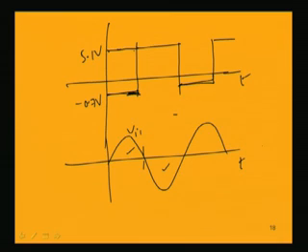In order to use it for digital circuits, we require a voltage not beyond around 5 volt for a 1 level or high level, and around 0 volt for the 0 level. So, the zero crossing detector output was too high for digital circuits.